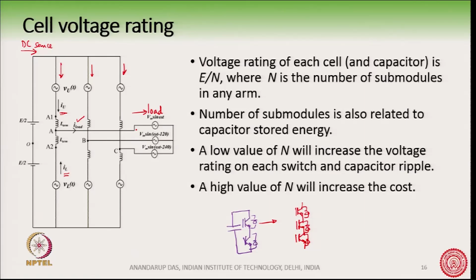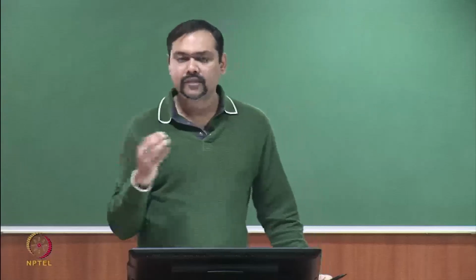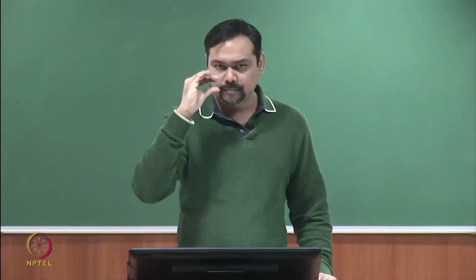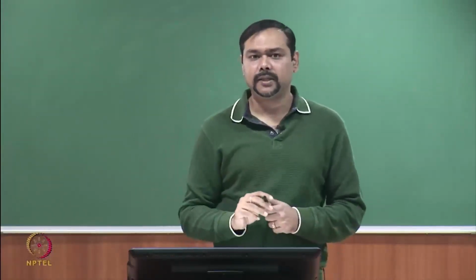Why are these arms needed? Because they are creating this multi-level sinusoidal voltage source. They are very much needed, and it is important for us to keep the capacitor voltages at a fixed value. If the capacitor voltages are going up or going down, then we will not so easily get the sine wave output. If the capacitor voltage is diverging, we will have a non-sinusoidal output. This we have seen earlier also, that if the capacitor voltages are not kept at a particular value,